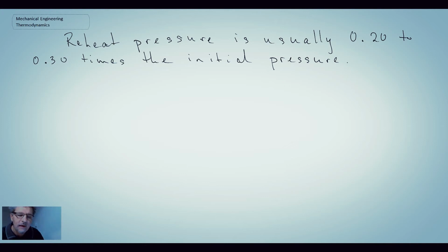The second thing is that the reheat pressure is usually about 20 to 30% times the initial pressure that we have. And finally, ultimately, we could do reheat many, many times, but the economics really prevents it. And so due to economics, typically only one reheat stage is employed.